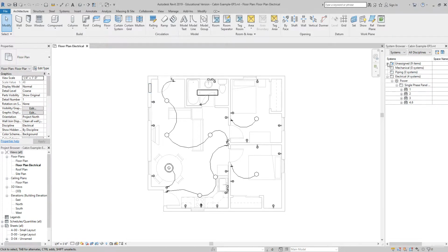So once we're sure we are all done, we are going to create what is called an electrical circuit schedule. Basically, it's going to tell us which circuit numbers, how many items or elements they have on them, and their location and the voltage that they use. This would be a very handy piece of information. So we're going to create that, and we're going to put it on its own sheet to print following our electrical plan in a packet.